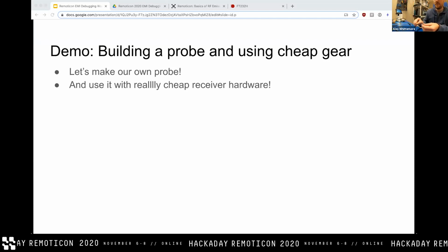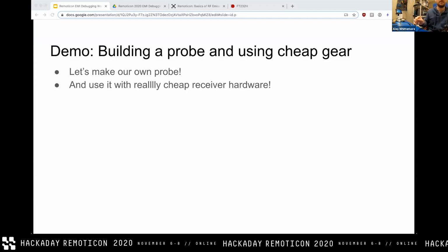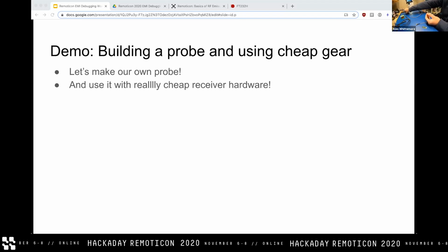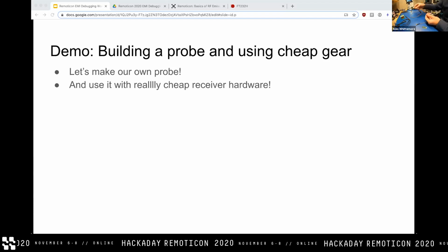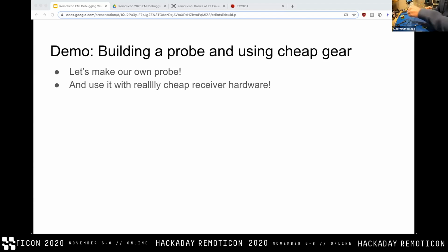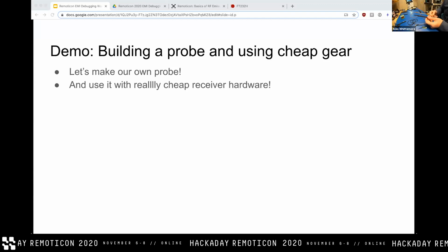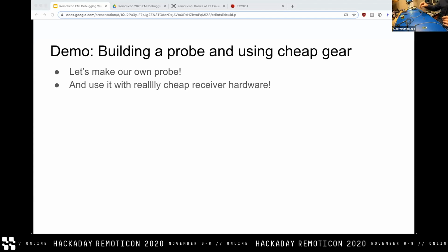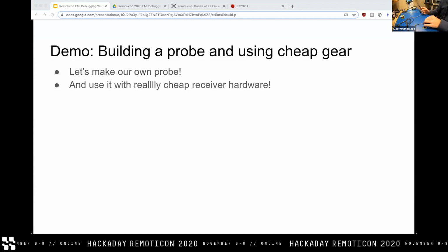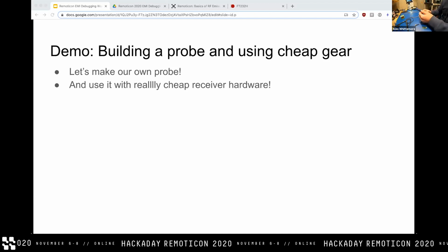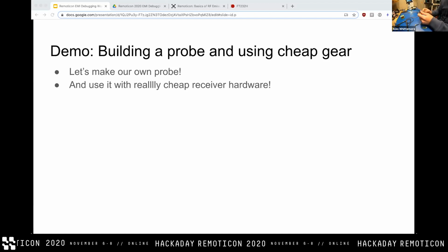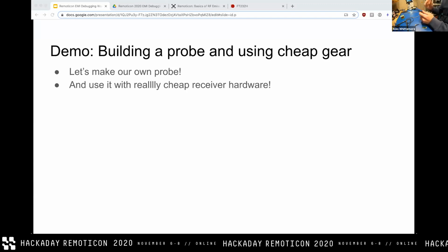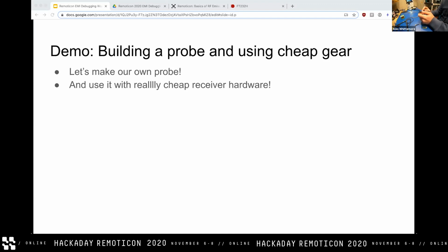This might be impossible to see, and I preemptively apologize if it is. If this is roughly equivalent to this guy, albeit without any shielding, then these two are roughly equivalent. And really all we need to do is make a loop of wire as small as we can possibly get it. There are a couple of key differences that I've found in practice don't appear to actually matter all that much. One key difference is it's really important where the active area of the probe is, and the definition of active is where there is and isn't shielding, at least nominally.